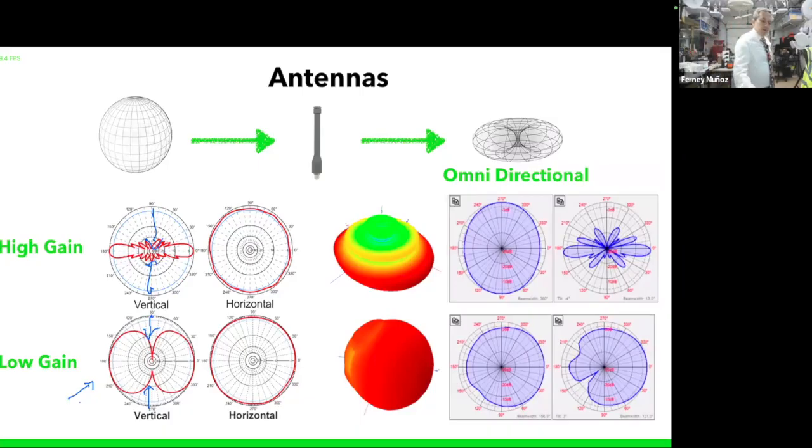Toys R Us, you know that, the toy store? They had a problem at a warehouse. Well, now they have a bigger problem. They shut down all the stores. But years ago, they had a problem at a warehouse. And then the Wi-Fi was low. The scanners didn't work quite well. So they got these high gain antennas. And now the scanners didn't work at all. They had to go to the very end of the building to get signal. It's a stupid thing, it's just not working. We got this really expensive high gain antenna. It doesn't work. So they got the guy to troubleshoot. So like, wait, why did you buy high gain antennas? Oh, because, you know, high gain is better than low gain, isn't it?